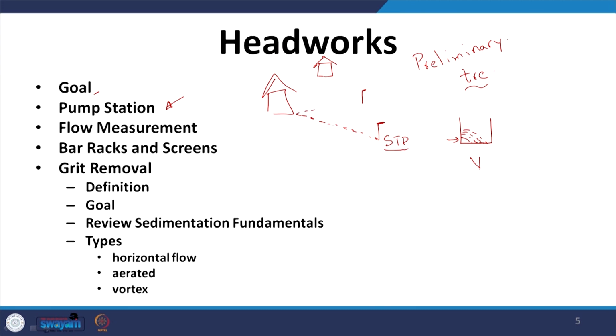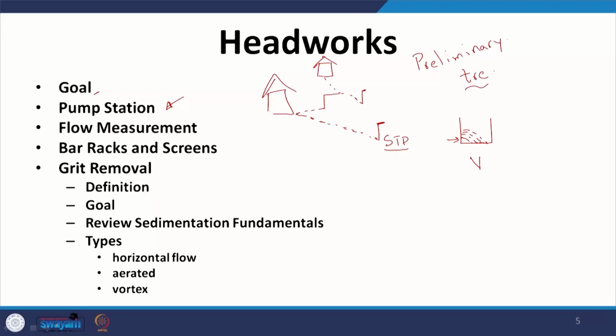You can try to have pumping stations so that this sewage joins here and ends up at my STP, but pumping stations for wastewater treatment are not a sustainable solution in the long term, for bringing up the sewerage from one network to the other that is at a higher height.